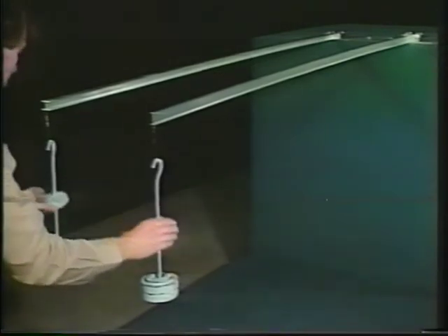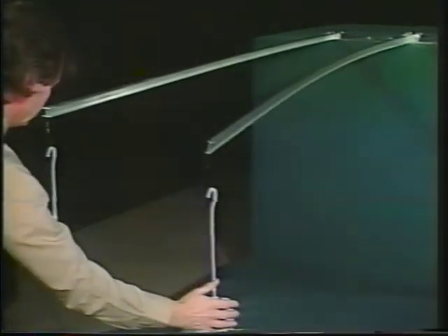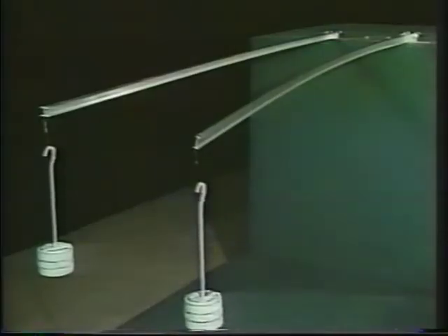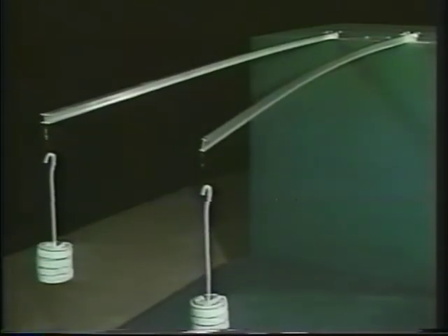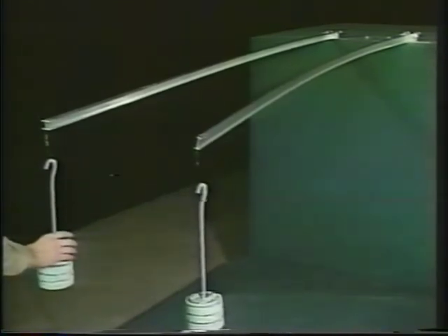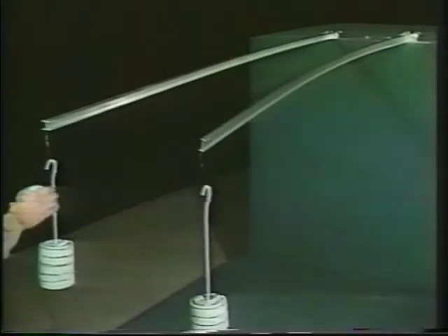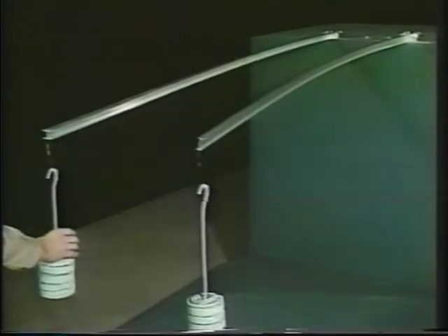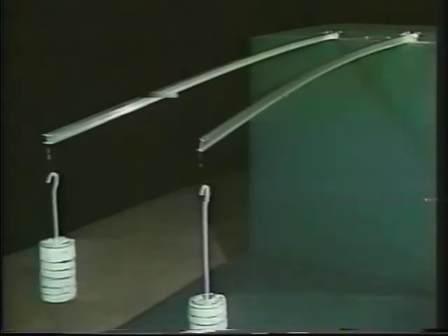However, for the beam with low minor axis stiffness, as loading progresses, instability intervenes. The cantilever on the left does not suffer any instability and would eventually fail by plastic action. Lateral torsional buckling is only likely when a section has significantly different values of second moment of area and is subjected to bending in the stronger plane.